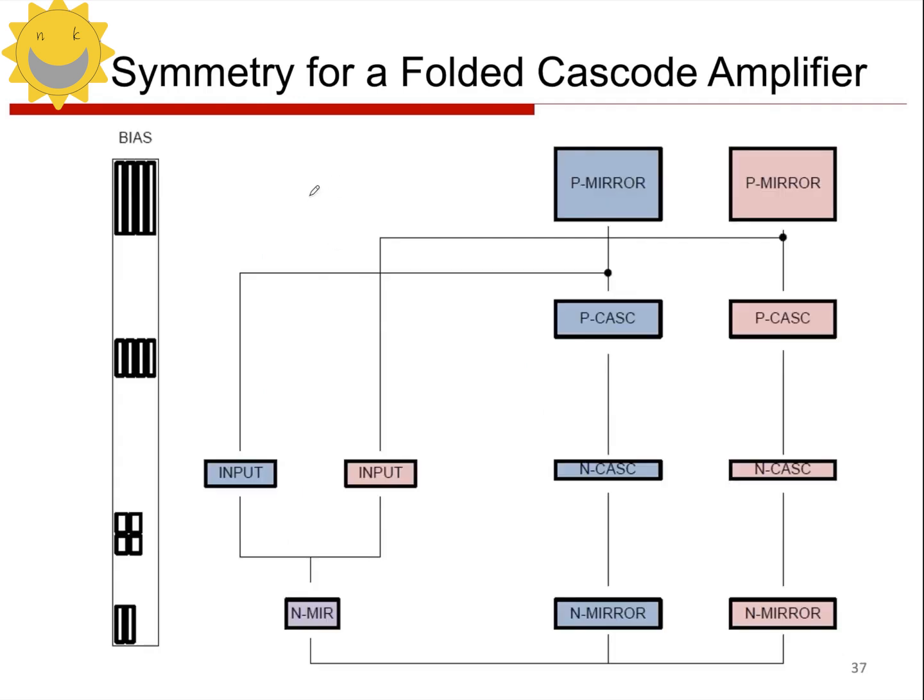First of all, we put all the components here, right? We just talked about this. This is the input pair. Then we separate the positive and negative paths, one with the blue one and the other with the light pink one, to distinguish them. Then our goal is to match the blue one with the light pink one, right? If the characteristics of the transistors can be made completely identical after processing, then clearly the matching degree of this operational amplifier will be quite good. In the end, its offset voltage will be very low, and its power supply rejection ratio will be very high.